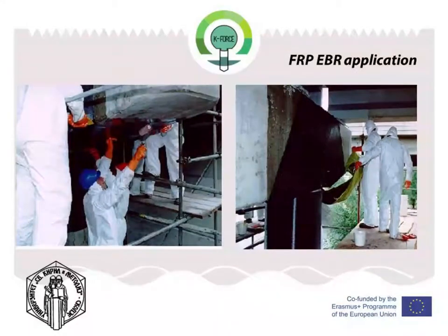The application depends on the type of externally bonded FRP reinforcement. For strips and laminates, the adhesive ensures bonding only. For sheets and fabrics, the resin ensures both bonding and impregnation. The application of externally bonded FRP reinforcement is performed according to the specifications given by the manufacturer. The adhesive is applied as a thin layer to the concrete immediately after mixing.